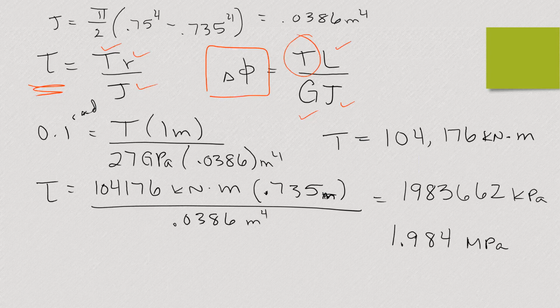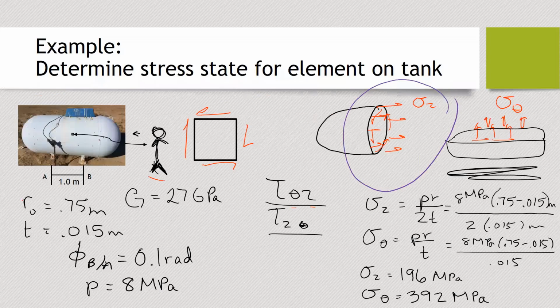Okay. All right, so now we have our stress components. And it's important, I want to point out that if we go back to the previous slide, we have two distinct normal stresses. And yet, even though we have two shear stresses showing up, we know that they're equal magnitude because they're just an expression of the same stress acting on the two sides. So we don't need to solve for any additional stresses. So we have our 3 values.